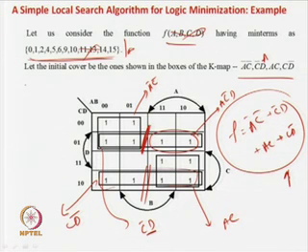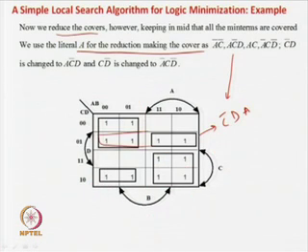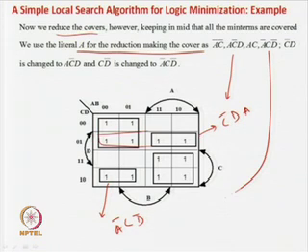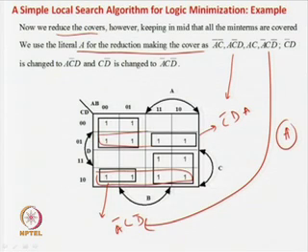So that also you have to break it up. If you break it up, you are going to get this term, which is nothing but a prime c d prime. So this is another term which is coming out. Initially you had a term something like this. Now what we are doing is selecting the variable or literal a and breaking the terms. This term was continuous, so this one will get broken. This was another term which will also get broken.